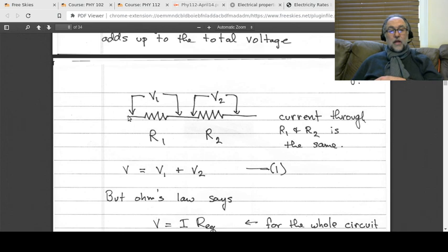And you put one of the probes over here, and you put the second probe across both resistors, and you measure the voltage across both of them. That's going to equal the voltage of the battery. So that's what I called V here. That's your total voltage drop.